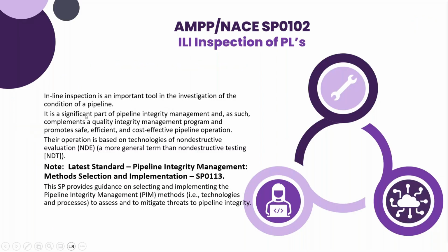I'm not going to get into the specifics of it, but I just wanted to get into NACE. Oh, let's go back here. SP0102. This is ILI, because everybody does ILI. At least they should be doing it. And of course, you need to look at that document, the standard practice 0102. They just came out with another document. Even the old document had integrity management, but now they've come out with a new one, pipeline integrity management methods, selection, and implementation. It's called SP0113.